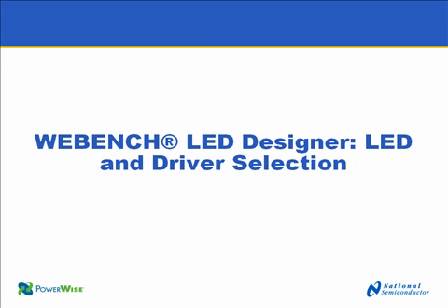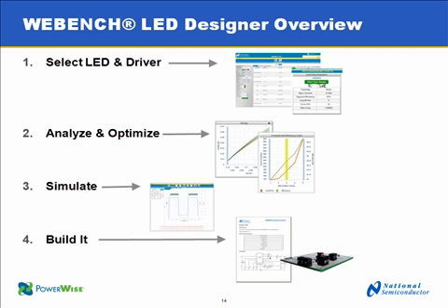Okay, let's talk about the WEBENCH LED Designer. Okay, an overview of this. It's got 4 steps. The first step is where you select your LED and your driver. The second step is where you would analyze and optimize your design. You're able to use SPICE simulation and calculate operating values over different voltages. You can simulate it using SPICE, as I mentioned. And lastly, we provide for some of our parts the Build It feature, which allows you to get a custom prototype, and you can also get a design report.